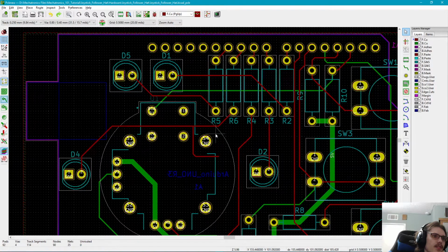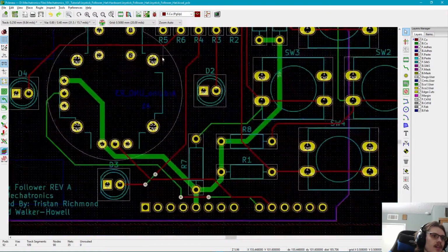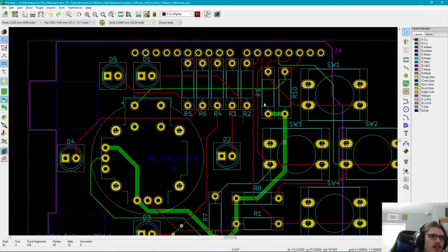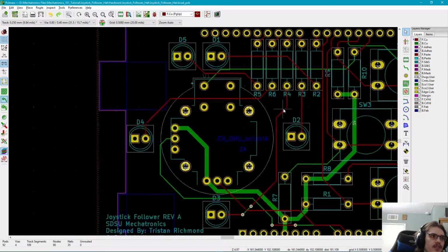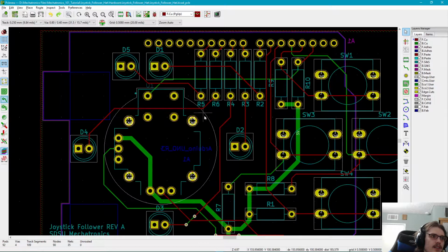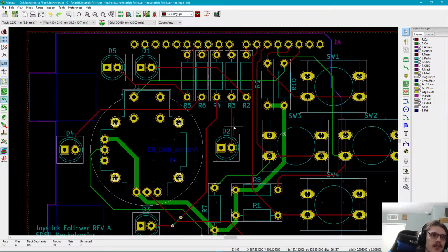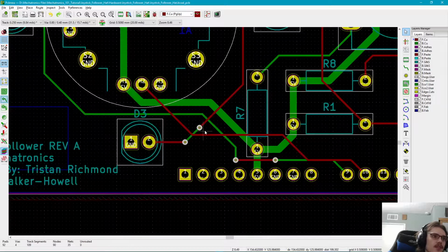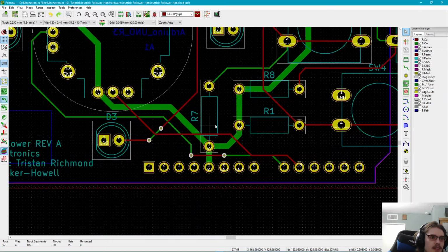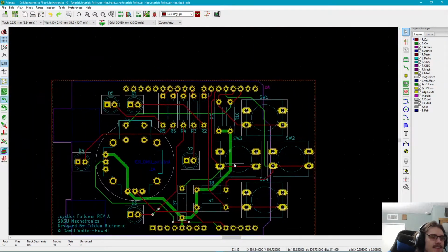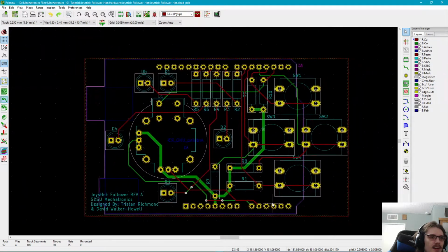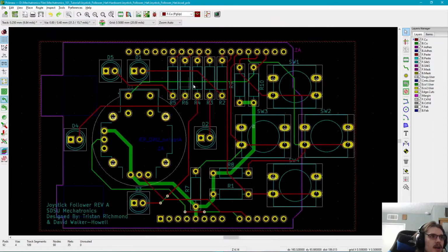Let's see, anything else that I can think of before moving on past this? So yeah, just avoid right angles. If you have islands, make sure you connect them to the plane with the vias. If you want to cross stuff, use vias to get to the other side, like a bridge. It's like interdimensional traveling. It's pretty good stuff. Yeah, I think that's about it.